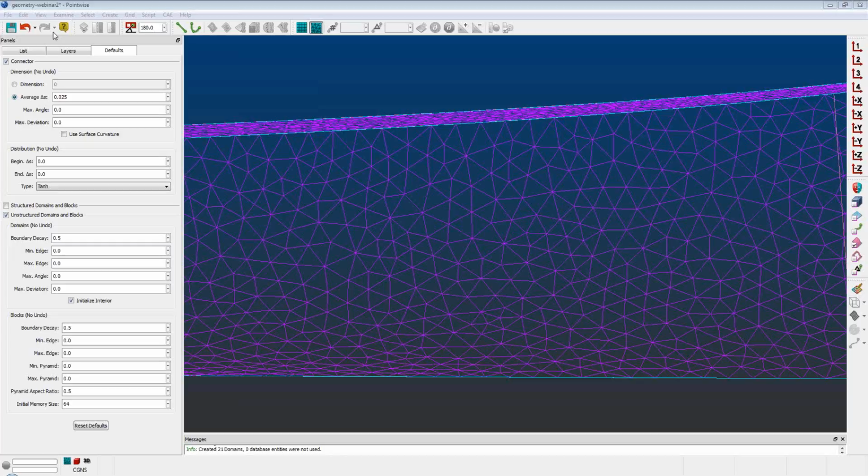There is. There's not a direct way to do it in Pointwise. What I would recommend in a case like that is to read in your STL file and then put a quad mesh on that. The quad mesh you can then export from Pointwise and re-import as geometry. On that you can apply the smoothing tools. If you need to at that point, you can smooth it out using any of the smoothing tools in Pointwise.